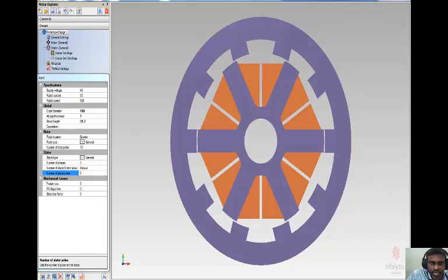If you see here, the first thing, go to the start and open the switched reluctance machine page. Click the new button. In that we have 4 machines as far as MotorSolve is concerned now: DC machine, induction machine, switched reluctance machine, and permanent magnet machines. Choose the switched reluctance machine, then you get a window like this, and click the prototype design.